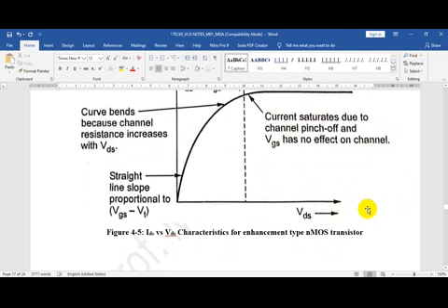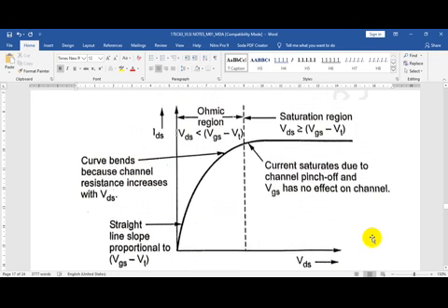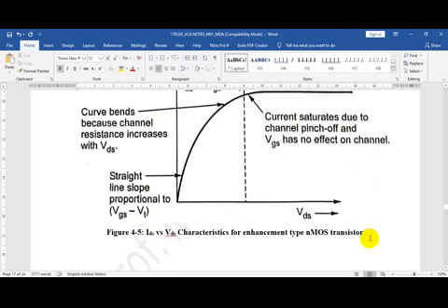This is a very important question, and also very important in understanding the working of a MOSFET transistor. In VLSI, we basically use a MOSFET as a switch because ultimately it is binary, either 0 or 1. In that case, the MOSFET is either operated in the cutoff region, wherein the transistor is completely off, or the saturation region, wherein the transistor is in on condition.